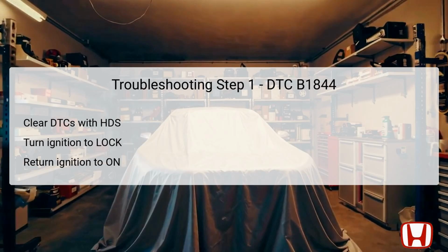The first step in the troubleshooting process for DTC B1844 involves clearing the existing diagnostic trouble codes using the Honda Diagnostic System, abbreviated as HDS. This action resets the system, allowing the technician to gather accurate diagnostic information post-clearance.